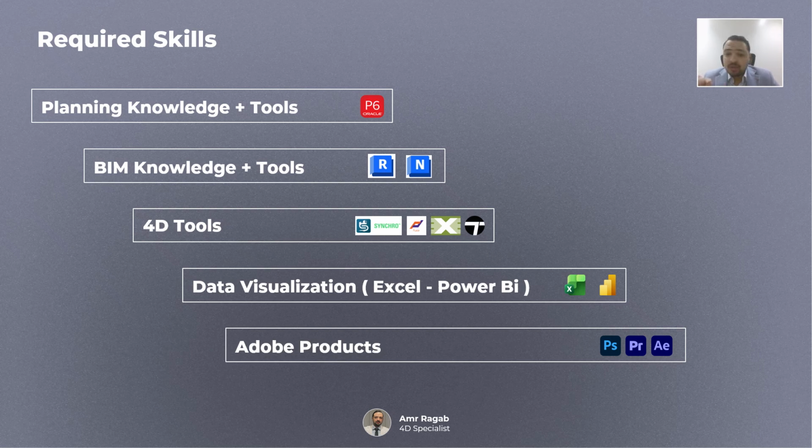And in this part, there are many tools you can use to integrate the process. You can develop Revit API plugins, or you can make mapping sheets, or you can make Dynamo scripts. As you know, a Revit model is a structure. You can convert it to an Excel sheet with tools like DiRoots One.